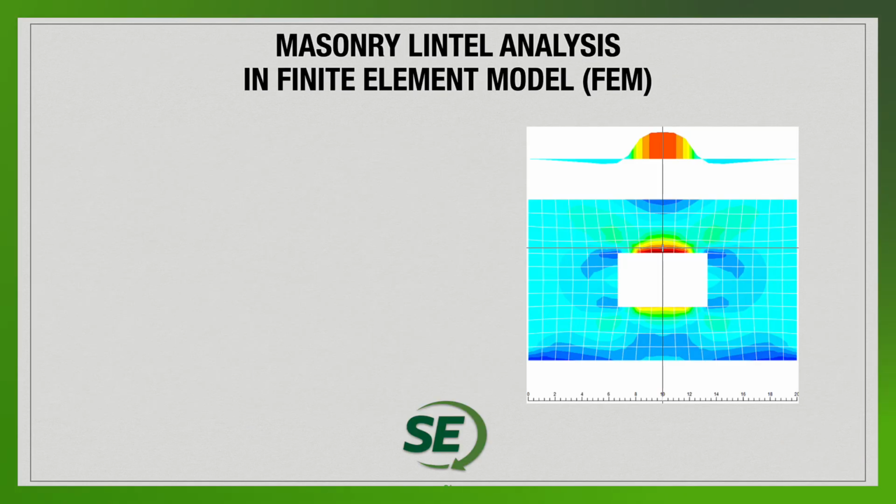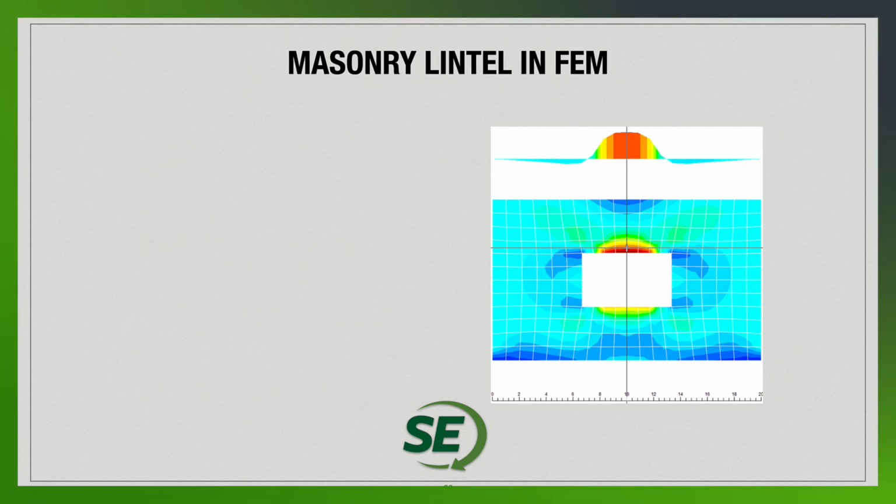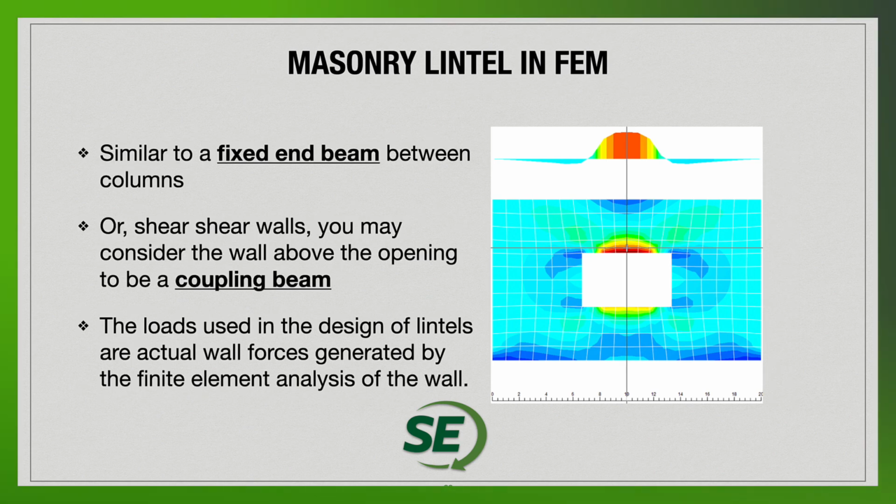Again, remembering that having finite element analysis is going to be pretty important if we want to consider all the different stresses and forces that you would have for these elements, and making sure that we can understand how the forces would, is it arching action, not arching action? What are some of the different fixities that you have? How does that correlate to the overall forces that you need to design for? Then that really does require us to also understand where the different movement joints are, understand that the lintel elements are going to be more like a fixed end condition, and then with that, how the forces kind of move through.